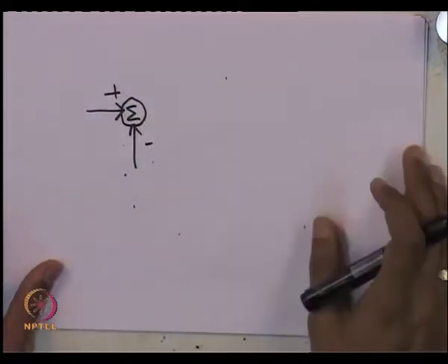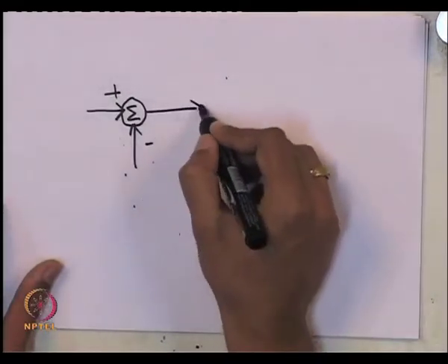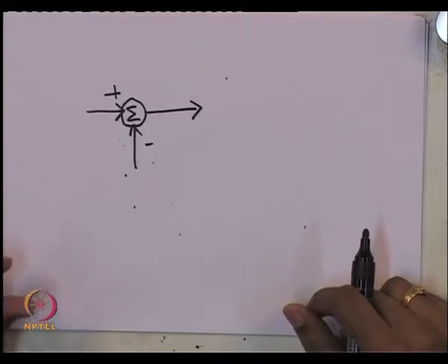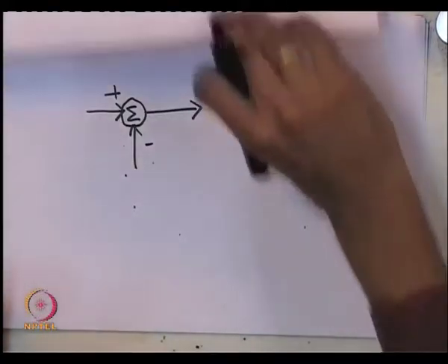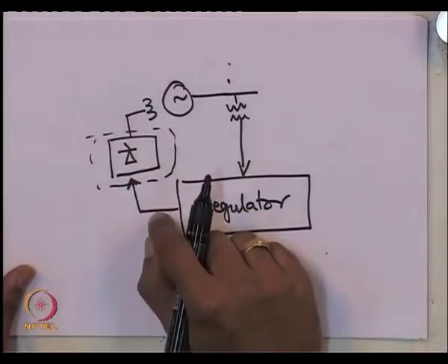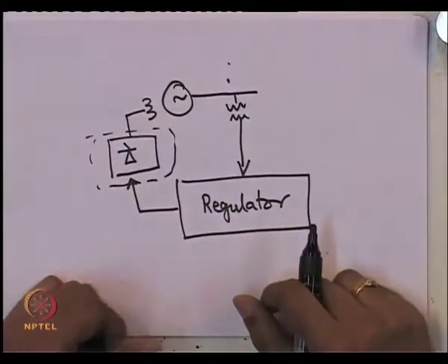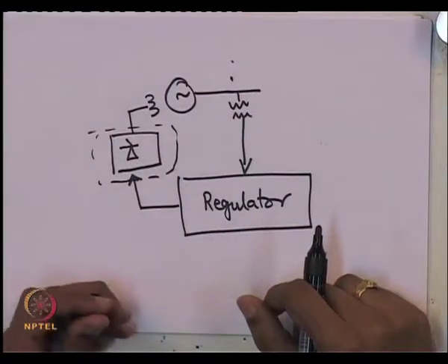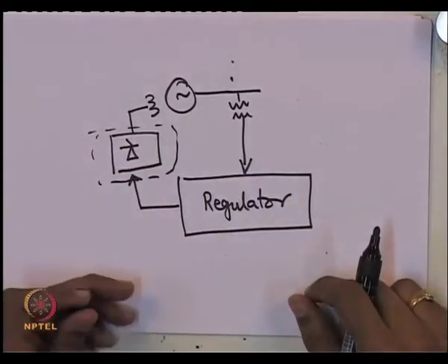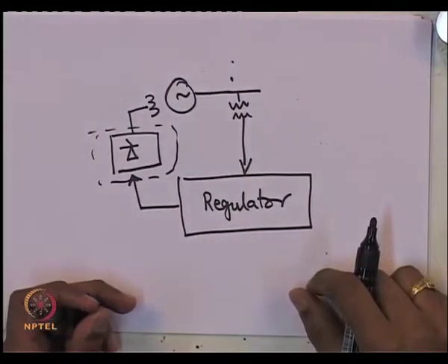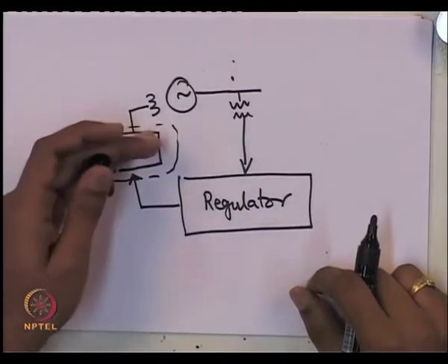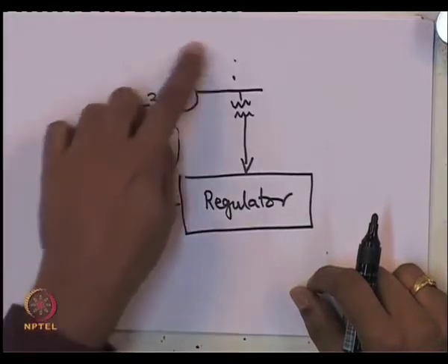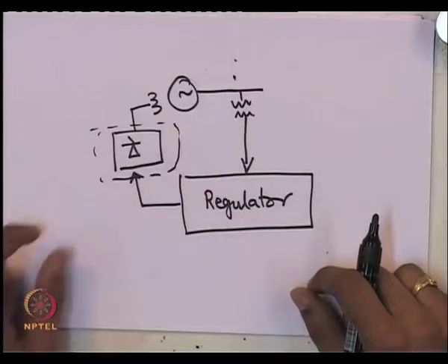It basically consists of some hardware which tries to implement certain mathematical functions. Remember that the control signal to a thyristor bridge is not what is known as a high power signal. It has just enough strength to convey to the gates of the thyristors to delay their firing. So, the power levels used by a control system are much lower than the actual power rating of the apparatus it is trying to control.